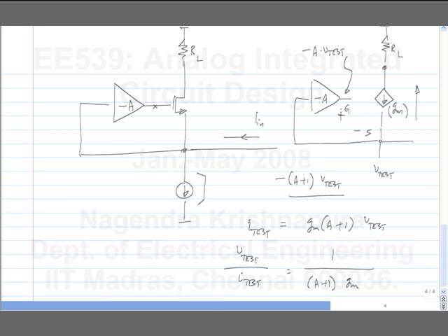So it's an even better current buffer, and it can also be used as a common gate amplifier, or basically a current buffer. I shouldn't call it a common gate amplifier because the gate voltage is not fixed. But if you feed in some current I in, the same current flows here, and the impedance looking in here is very small, and the impedance looking at the output is very large. So that's how we can make current buffers or common gate amplifiers.